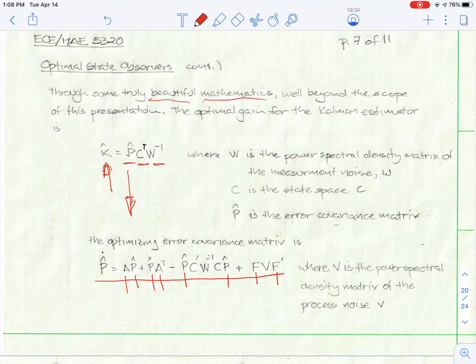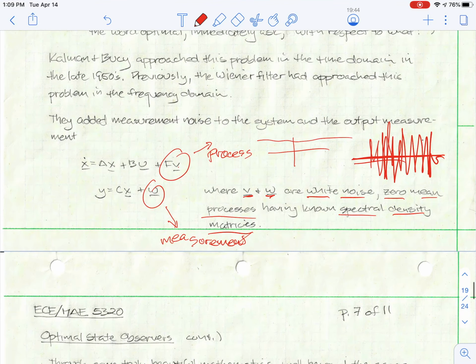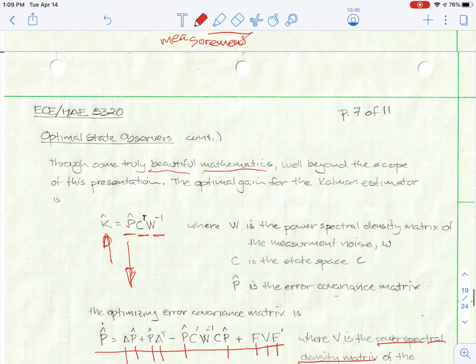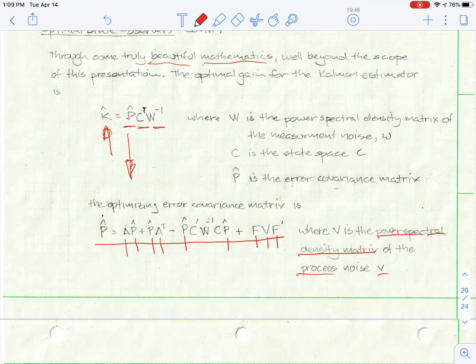This is your process noise multiplier, and this is the power spectral density of your process noise. So that process noise vector that you had right here, and the F they had there, those incur there. So officially, in order to create a Kalman filter, I'm going to have to solve this thing, and there's a couple of things that you can do.